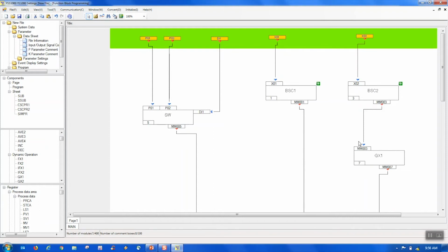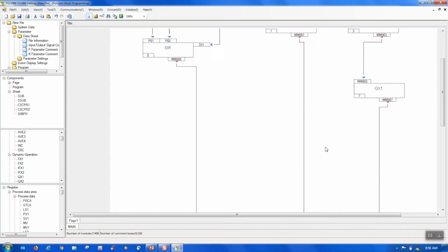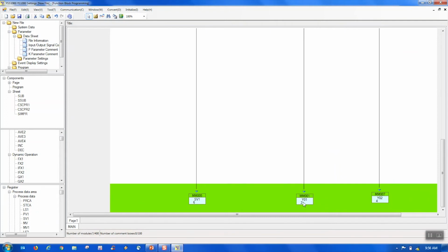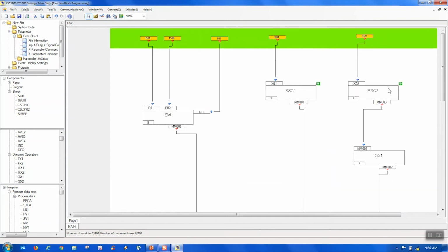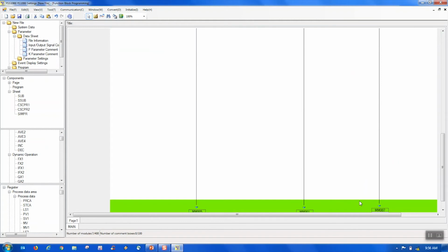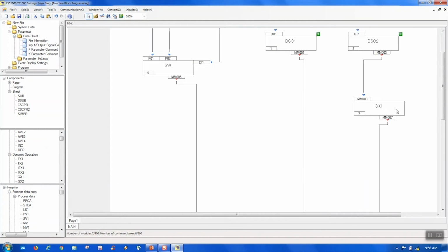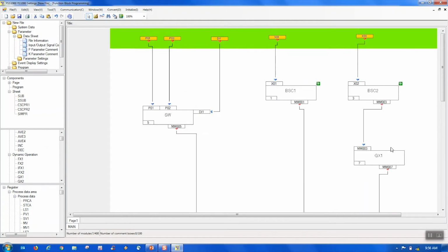And one thing you may notice now, in the bottom left-hand corner of all these blocks, you'll have numbers. Those are order of execution numbers. So this block will be executed first. This output is second. Basic block 2 is third. The output is 4. And then we have this g of x, which is 7. So this means that the output actually gets written to before we do the g of x conversion, which could cause some problems down the line.